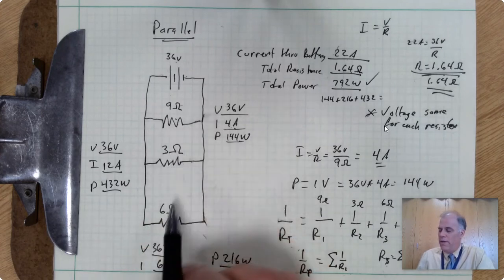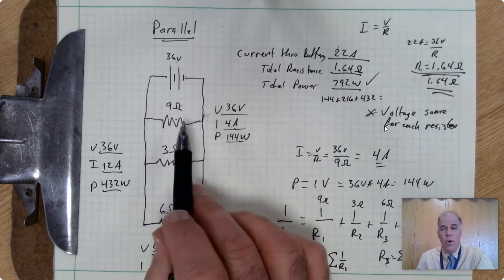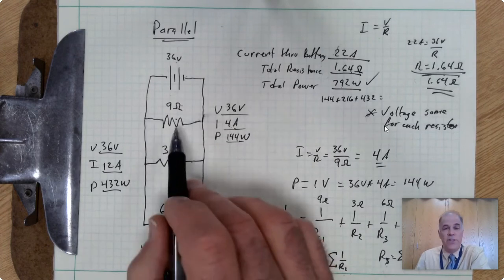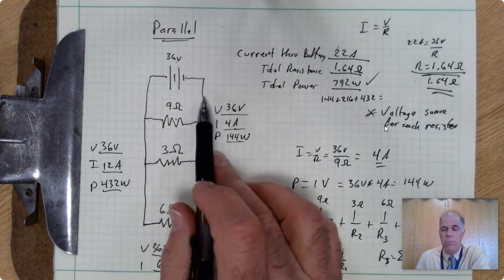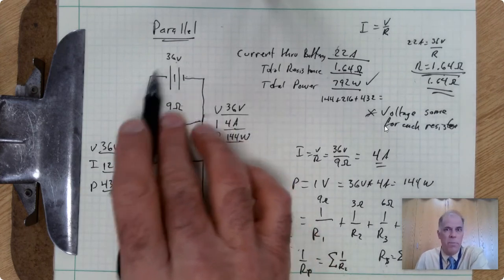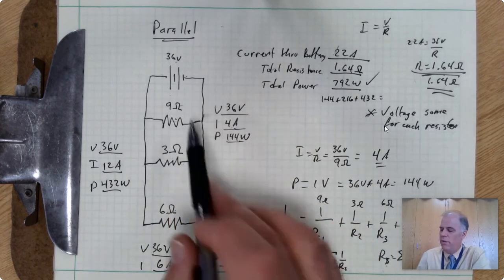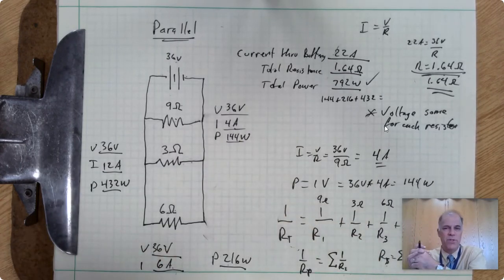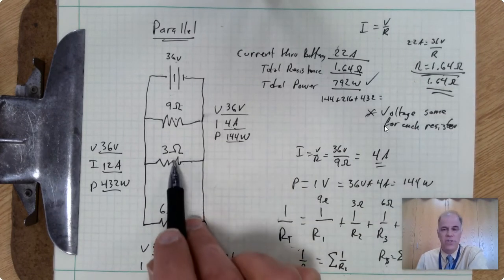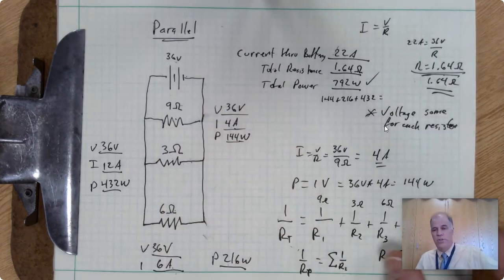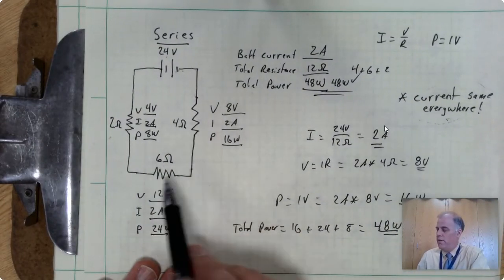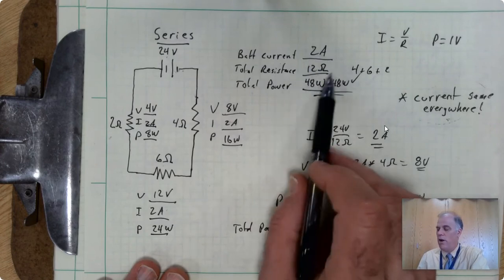But if you open up another pipe, even though it's an even skinnier pipe, a smaller diameter than this one, it's still going to let a little more water flow through, which means that more water is going to be coming from the pump, if you will. So the equivalent resistance, the equivalent of how big or how small the actual pipe is, that total resistance, will be smaller than the smallest resistance in the resistance in parallel.